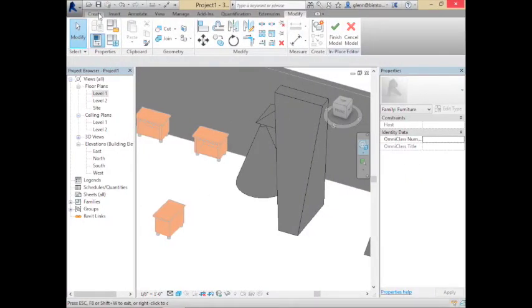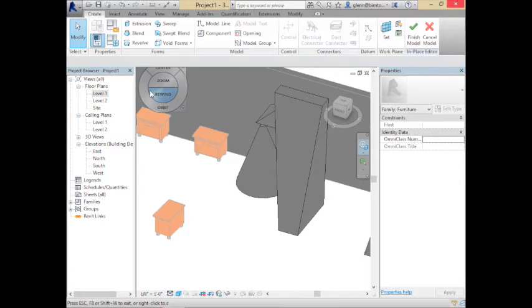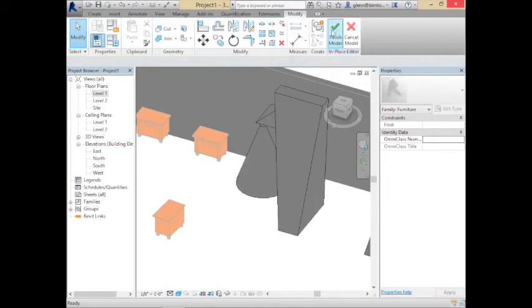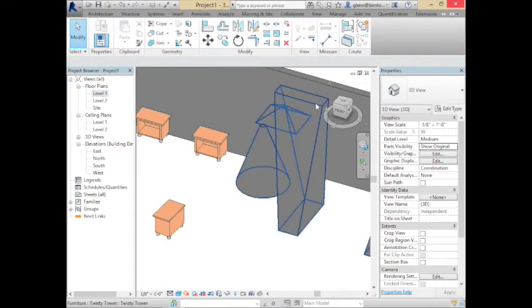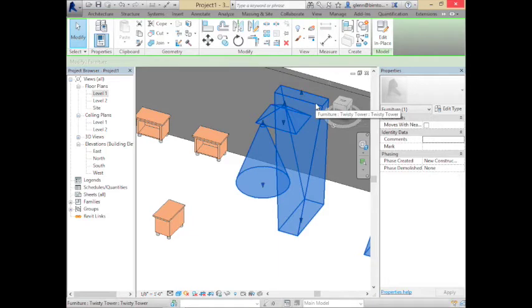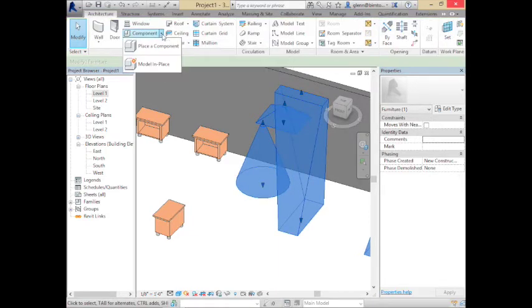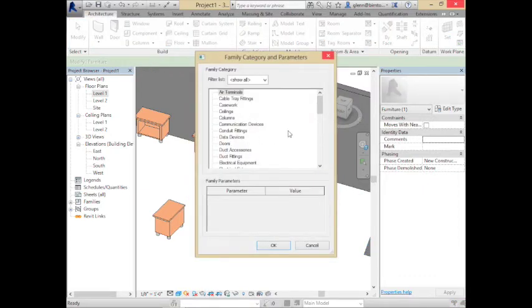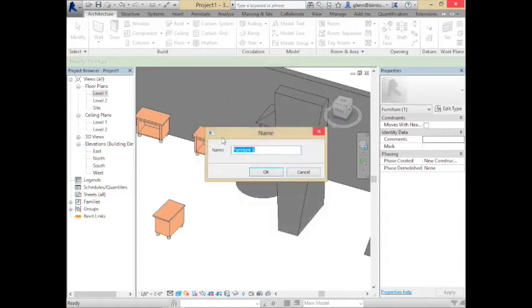In Create Mass, we are going to choose the sweep as a type. Actually, let me go ahead and close this model, just so I can make the sweep a separate piece. I'm going to have all these blends be a separate little thing over here. So I'm going to create a new in-place model. Okay, and we'll make a sweep. So, oh, what will this be? I'll just make it a piece of furniture also.